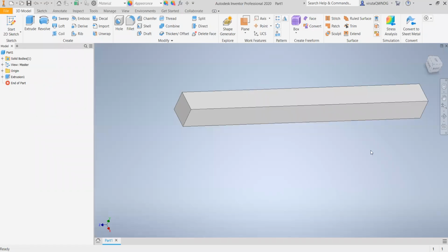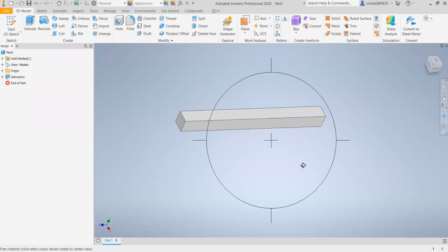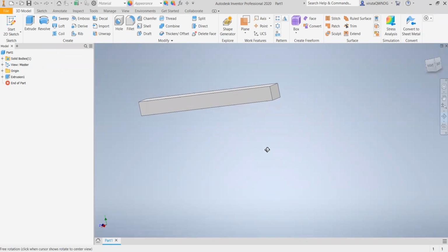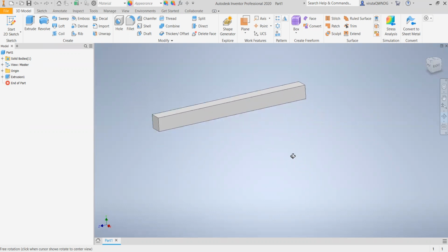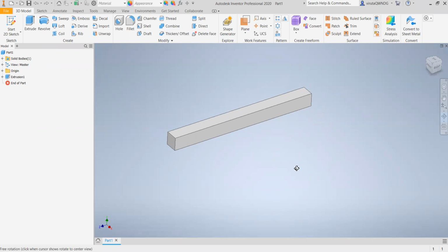Hello, we are going to do just a simple finite element analysis for this 2x2 bar. We are going to apply some forces vertically, apply some fixed support. We'll be able to assign materials, check the mesh, and find the solution, the stress vortices, and the total displacement.